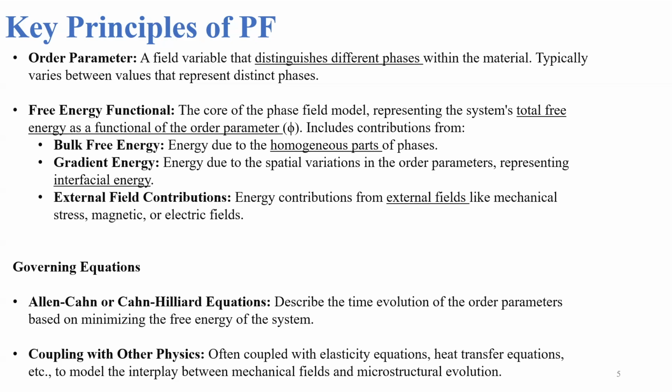So if you want to understand the energy of the homogeneous part of the phase, the energy that comes from the gradient between one phase and another phase, and any external fields, such as mechanical stress, magnetic field, or electric field. If you understand these three things, that is, suppose there are two phases, if you understand the contribution of one phase versus the other, the gradient between one phase and another, and the contribution from the external field, then we can formulate the free energy functional of the phase field.